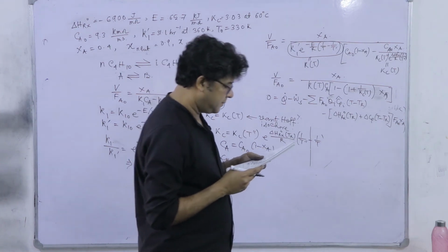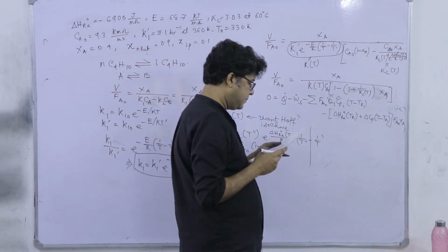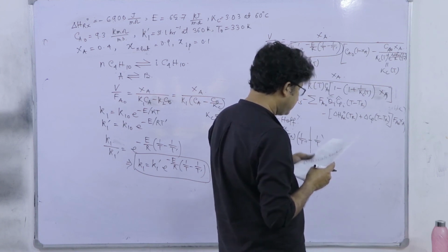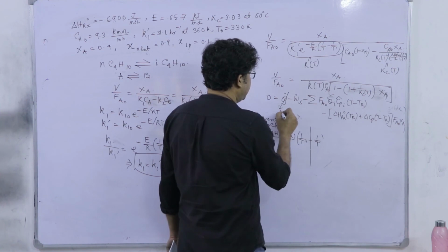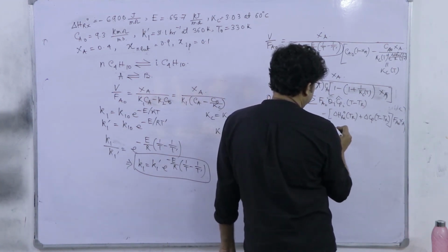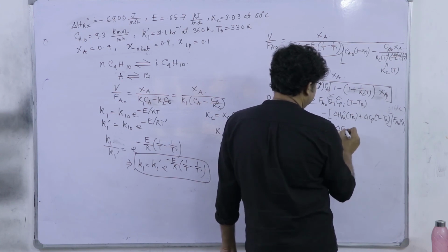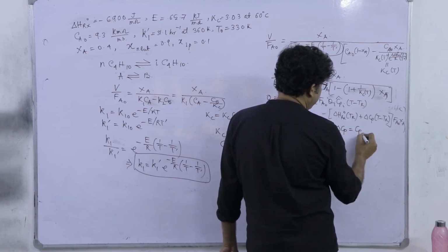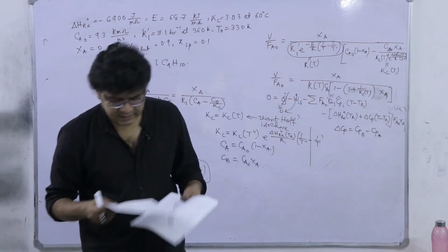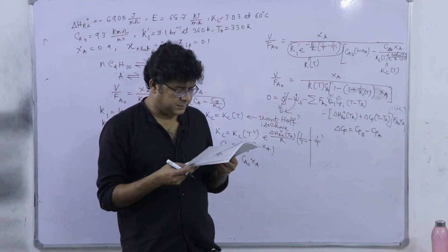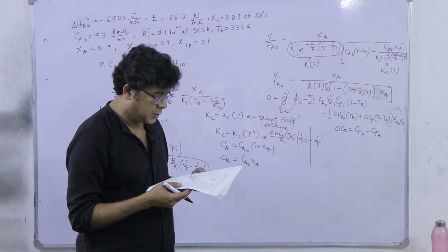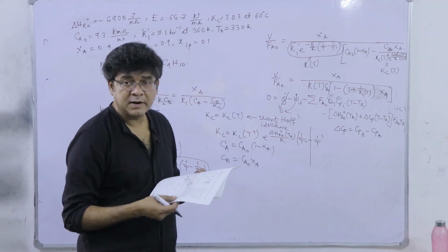So, from there you see Q dot is zero, adiabatic, and this W dot is also negligible. So, this delta Cp is Cpb minus Cpa, and what is given in the problem statement is that both the specific heats, Cpa, which is N-butane, and Cpb, which is N-pentane, are 141 joule per mole per Kelvin.